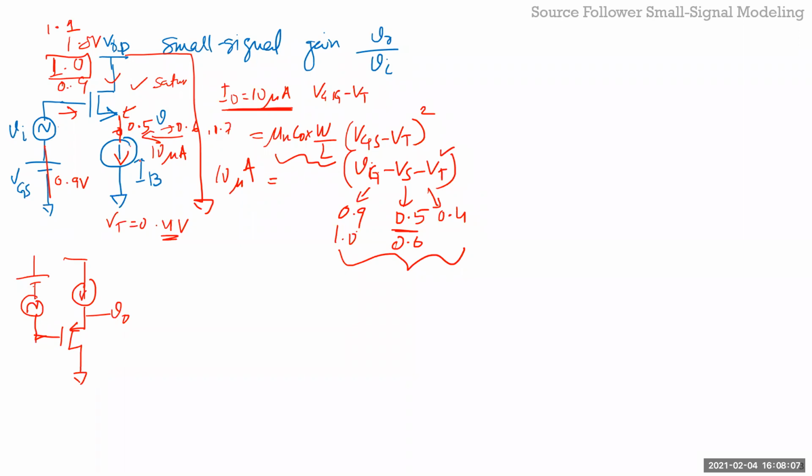So then you put a buffer like this. Then if it has the voltage to supply to 8 ohms, so let's say your headphone was 800 ohms, right? So you have 10x voltage to supply, but 8 ohms needs 10x more current too for that same voltage. So you have the voltage to provide to the speaker, but it just can't provide that much current. So you put a circuit like this, then it'll provide the current. So the voltage is provided by the amplifier, the current is provided by the buffer, right?